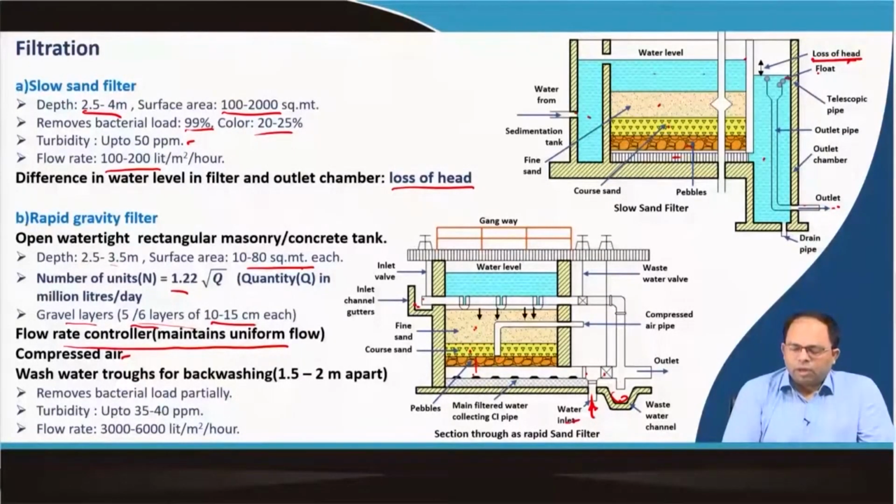And when water goes upwards during backwashing, it cleans the pores. It goes in the opposite direction and loosens them. Using compressed air we have already loosened the pores, and then we send water, and it cleans the pores. The water goes up, then we can open these valves, and the water can be collected into this pipe. We open this particular valve, and then the water is taken out through this outlet and let out. So, this is the wastewater, this is how it could be taken out.